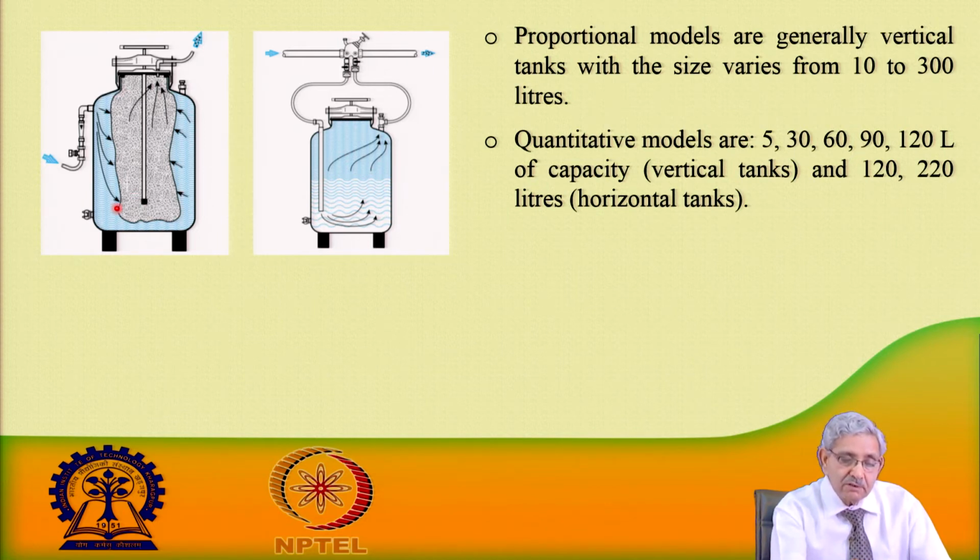So, there is water filled into the system, and inside this flexible bag the fertilizer solution is kept. When we are supplying water into the system, it presses the bag, and depending on the pressure, the amount of fertilizer will come out of the system and be injected into the pipeline.